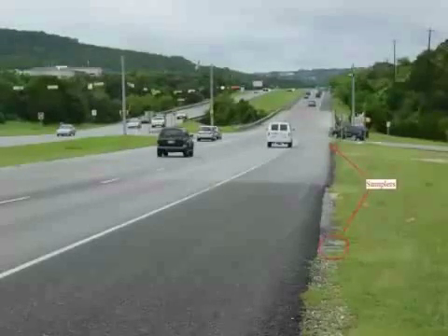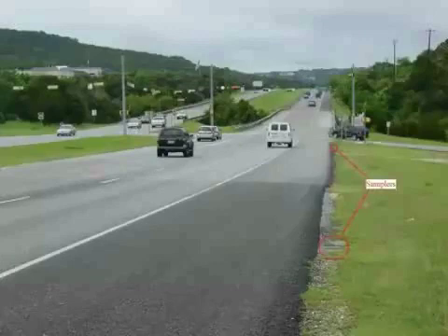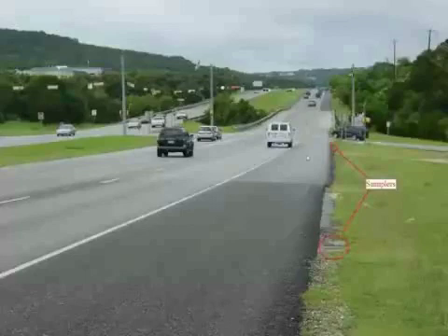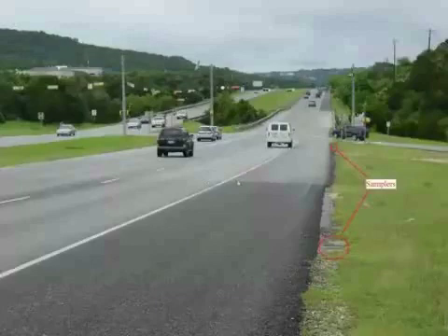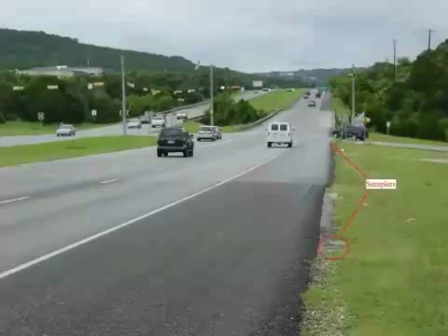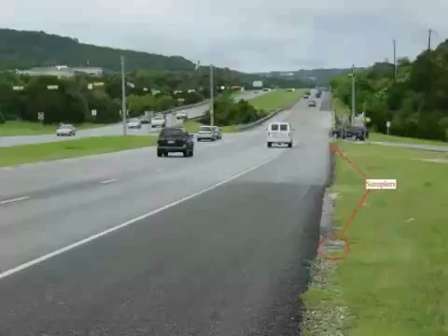And so you thought, well, that's unbelievable. So let's do a side-by-side test. And in this picture, the concern about PFC is that when you remove the fines, it loses some structural strength and tends to ravel, especially where there's sharp turning. And so you can see TxDOT in this case left the intersection conventional pavement, and then here's the boundary between the two. And then this is PFC down here, and we installed these passive samplers, one here and one up here, only say 100 feet apart, and we could collect samples from the same event. Next slide.